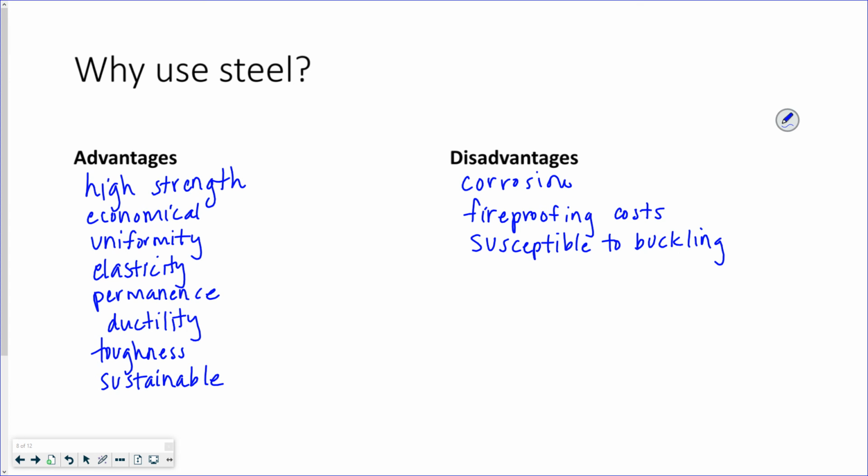And it can have failure eventually, due to fatigue, right? If you think about bending a paper clip back and forth, you'll eventually break it. Similarly with steel, if you constantly are putting on loads and taking them off, eventually it'll hit yield and ultimately deform excessively or break.